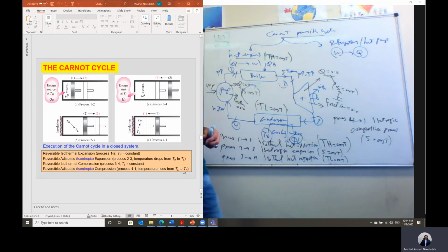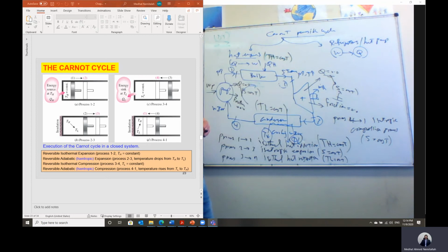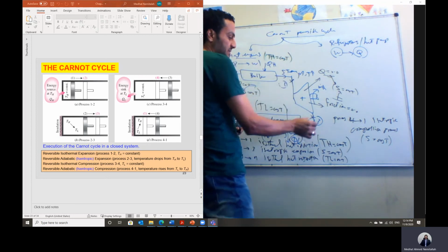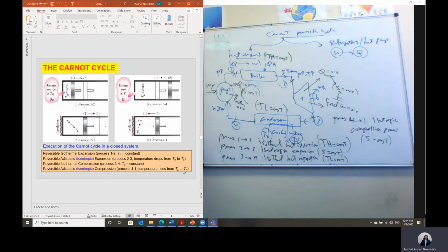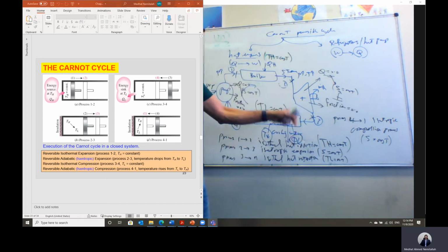I will give you more details in chapter 7. So if you have the condition before the steam turbine and the condition after the steam turbine, then we can assume the process for a reversible process is isentropic. Then we can proceed with the solution to calculate the work out of this system.